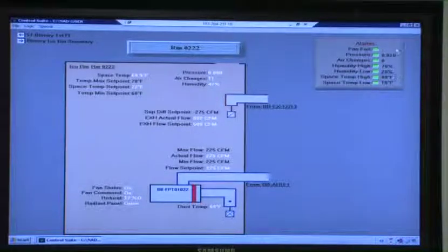We can go up there and change this once we get confirmation, because where we're gonna get that information from is that spreadsheet E&E's doing on all the air ventilation requirements for the building. Air changes and all that stuff, what is meeting code, the whole bit. And then we'll cross-reference those particular rooms that have all these controls on it, and then we'll make the adjustments and set points from there. That might be confusing, but does that make sense?